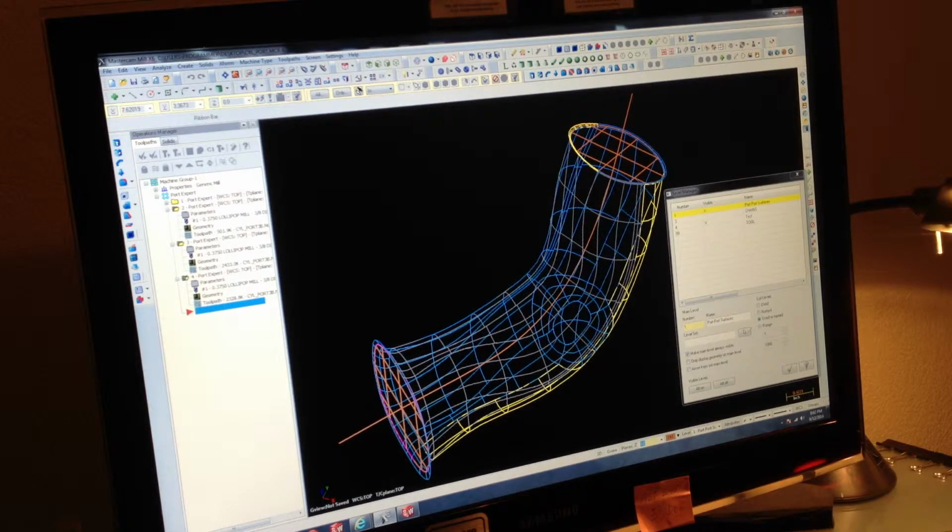Another thing you should keep in mind, you must always keep your vectors, so don't delete them, even if you don't need them. Put them on a separate level and always save them. The reason why I'm saying that is because sometimes your toolpath, the lollipop, follows the spline in the middle, and it violates the top and the bottom. Maybe it hits the bump or hits the top surface inside the port, or it might alarm out. So sometimes you don't get lucky in the first shot.